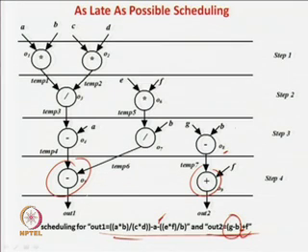You just put it over there. Now in this case, what is the immediate predecessor of 05? That is actually 07. 07 is this division operation, E minus F by the division. So just one step before this, 06, you schedule it at time step 3. Similarly 04: this 04 is the subtraction operation, this whole stuff minus A. It is also a predecessor of 05, so just schedule it one step before this, that will be time step 3. So in time step 3 we are scheduling 04 and 07.